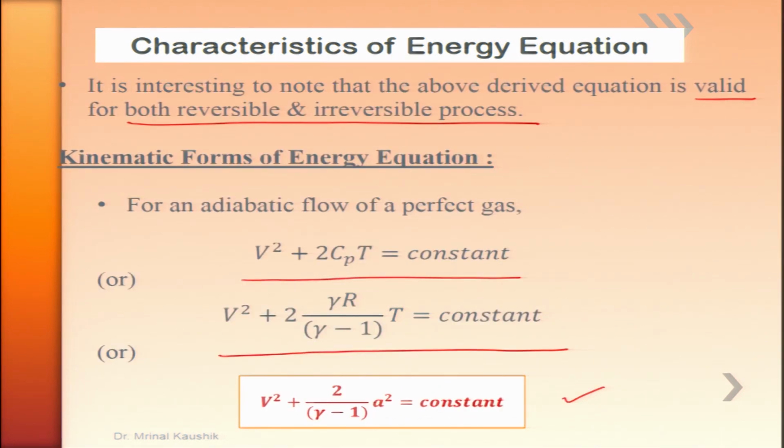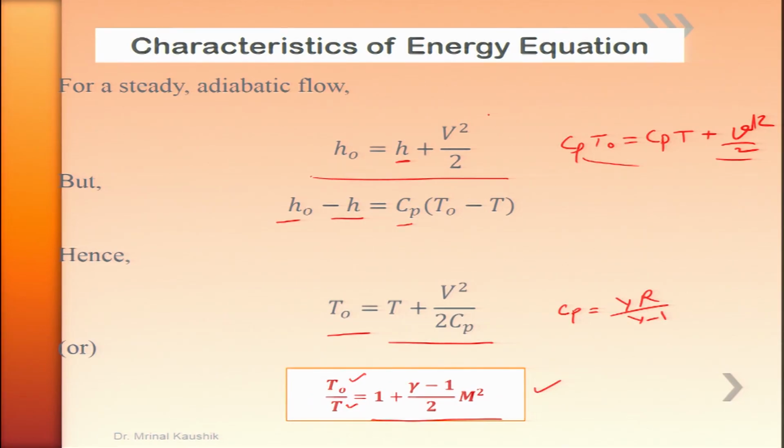Note that though we have used the adiabatic energy equation for an adiabatic inviscid flow, the temperature relationship between static and stagnation conditions is always valid for irreversible and reversible cases both. That means since it is evolved from the energy equation, this equation is always valid for both reversible and irreversible cases, and this eases our analysis a lot.